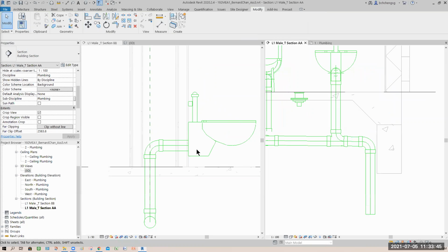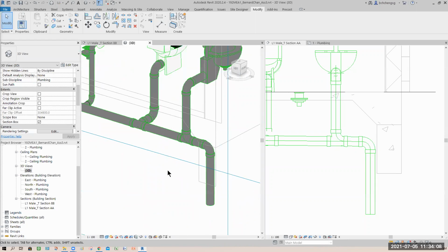Your Y joint, so when you flush, straight away should go down this way because they follow the sloping percent. If your sloping percent is the other way around, you flow inward, which is wrong also. All right, it should be this way, pipe down. So in the 3D, it should look like this, not like this way.